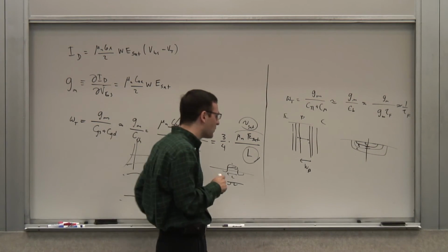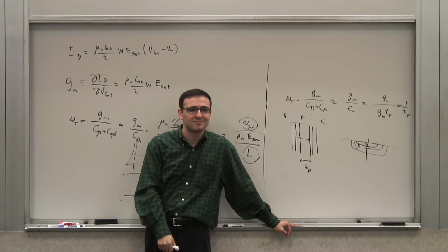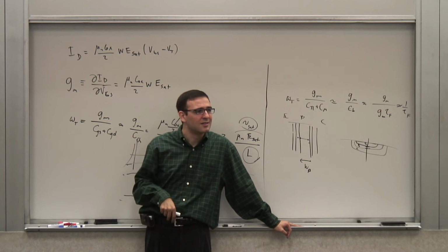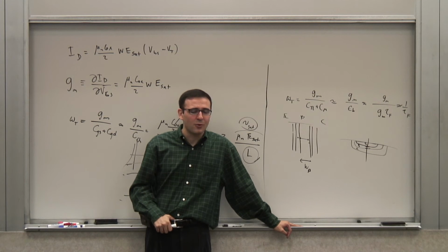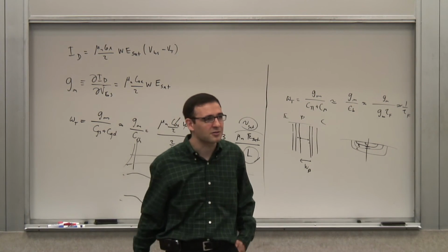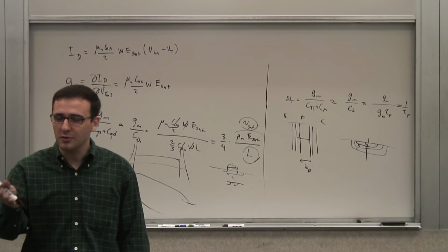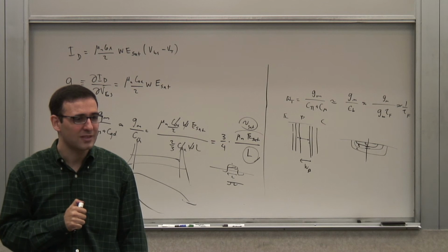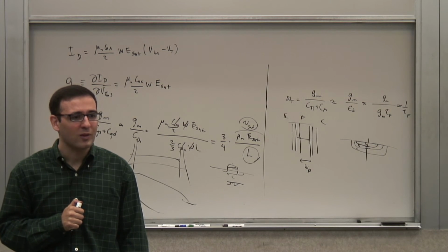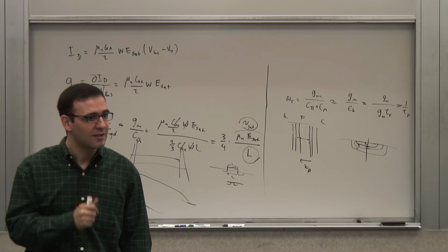But think about it. What is the wavelength of, I guess, visible light? Order of magnitude. 400 to 700 nanometers. Okay, order of magnitude of sub-micron, a little less than a micron, right? So it's 0.7 micron, 0.4 microns. Now, if you were to use visible light, what kind of resolution do you expect to get in this lithography process? That's how we make these.